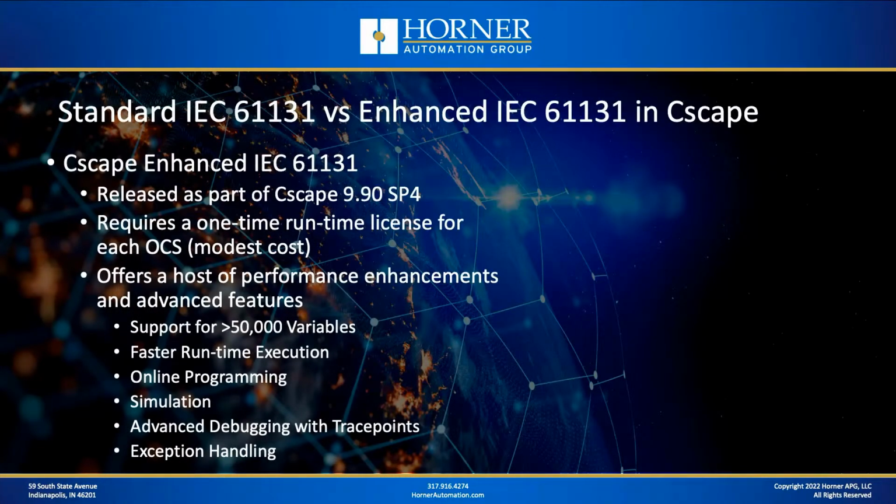Now, Enhanced IEC has only been around for a couple of years. It was released as part of 9.9 Service Pack 4. And it is a licensed feature, so it does require a very modest, one-time runtime license for each OCS that's executing it. Again, this is a one-time cost. It's not ongoing at all. But it offers quite a few advantages. What does it offer? Well, it offers support for 5 times as many variables. So instead of supporting 10,000 variables maximum, it supports more than 50,000 variables, so a lot more capacity.